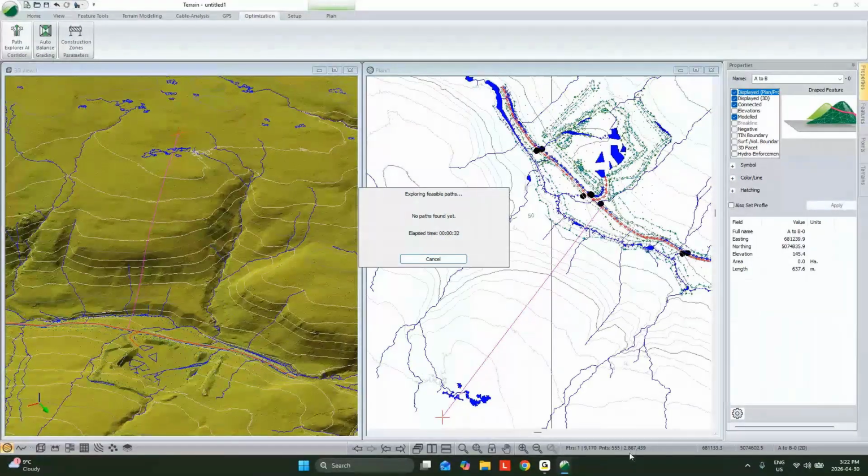Absolutely. All right, so Aaron mentioned it. Usually we recommend folks try to keep their number of modeled points to be less than 10 million, and that's a pretty conservative recommendation. It'll depend on computer specs, but down here is where you can see the number of points. So I've got the number of features. I've got just shy of 10,000 features, and I've got just shy of 3 million points in my file. If that was saying 30 million or something like that when I brought it in, well, then I'd probably want to do some thinning.